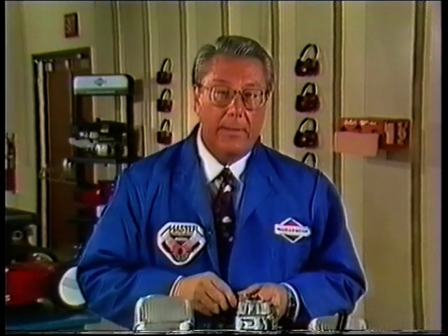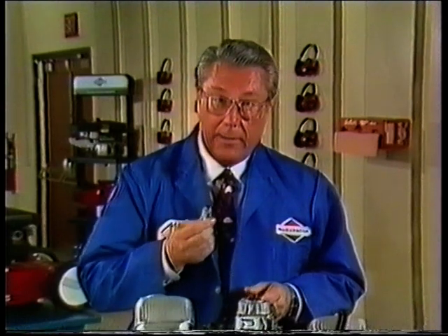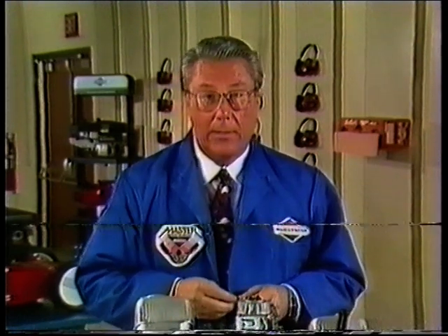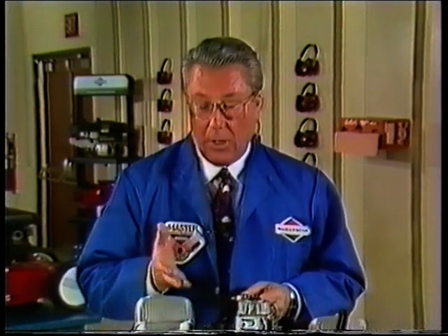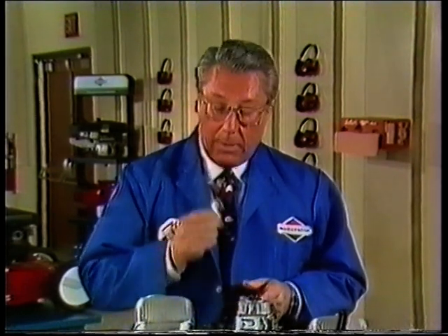If you've tried to start the engine repeatedly with the choke on or the engine properly primed and the spark plug is dry, then you know that fuel is not being delivered from the carburetor to the combustion chamber. This could be caused by a blocked main jet, improper venting of the fuel tank or bowl, or even an air leak between the choke plate and the combustion chamber. If, on the other hand, the plug is extremely wet, the choke may be stuck closed, or the engine has been over-choked or over-primed.